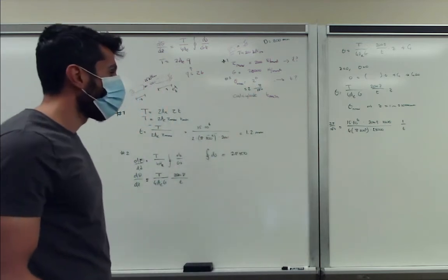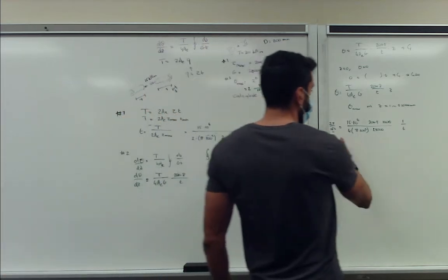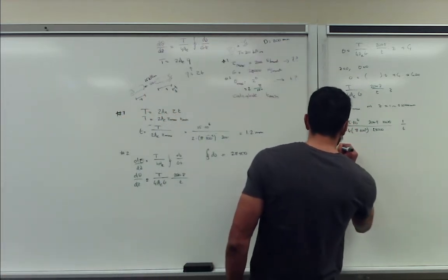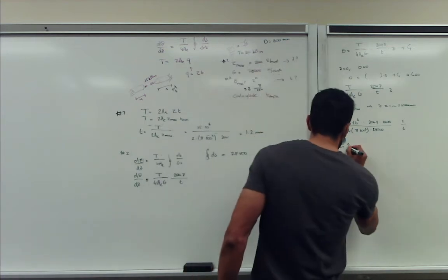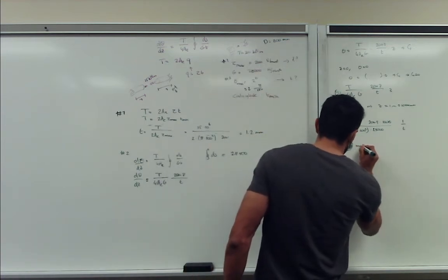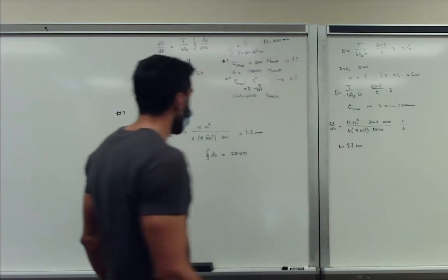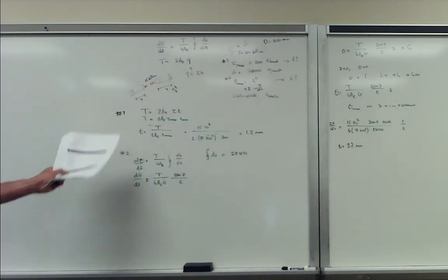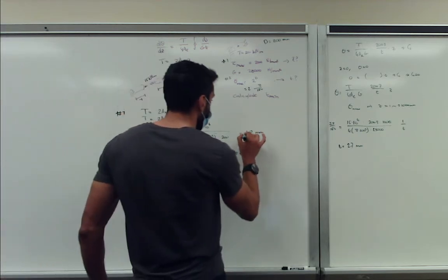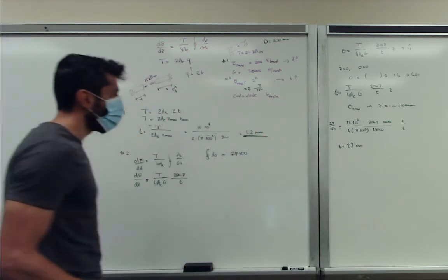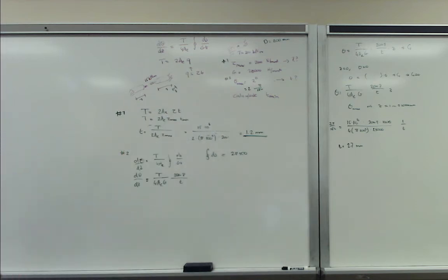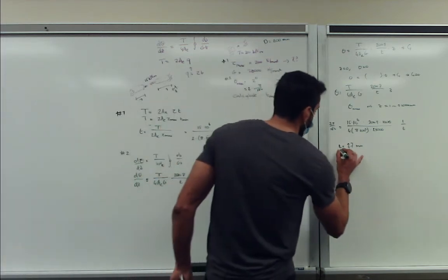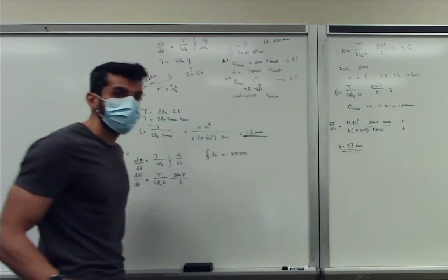Okay. So now again, we have one equation, one unknown. We can solve for t. And if we do this correctly, we get 2.7 millimeters out of it. So the key point is we have 2 requirements in the same problem. If we just look at the maximum stress, we can do with 1.2 millimeters. But if we also have to satisfy our second requirement, then we suddenly have to basically double our thickness.